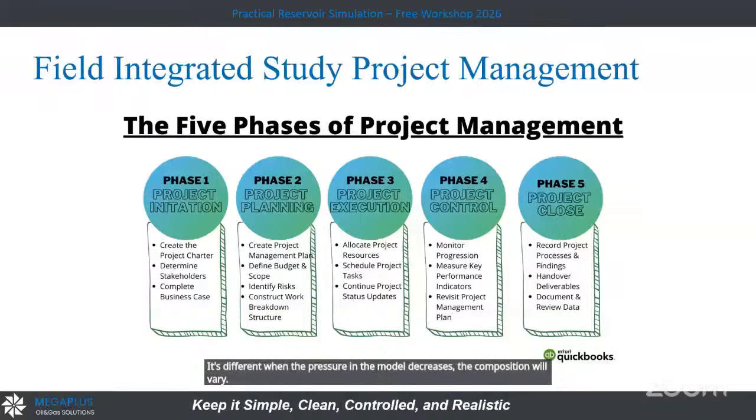So we have to take care of these conversions, and I have to minimize the iterations. So I have to make lumping of the components, I have to make coarsening, and near the wellbore I could make a local grid refinement and all of that. The key is to make the model smooth from geology until the fluid. You have to avoid any shock in the model, otherwise it makes a lot of iterations and can't continue. This is about the reservoir simulation.